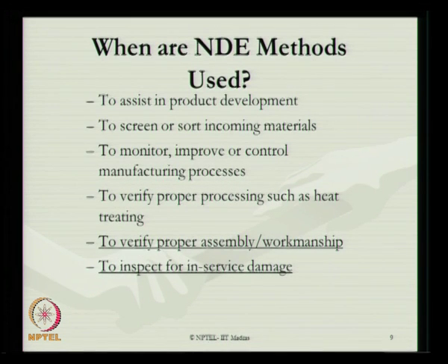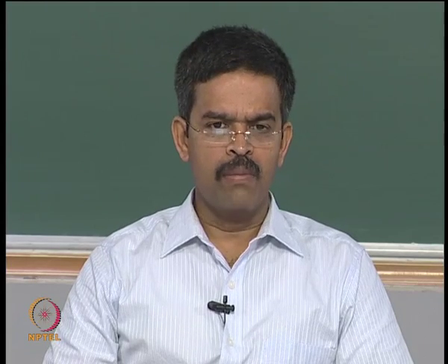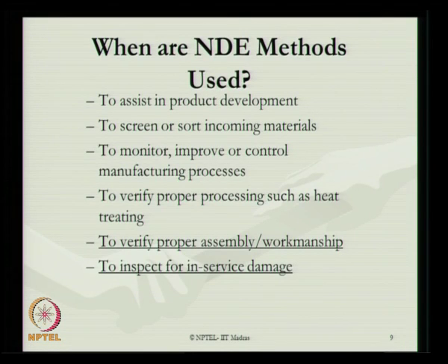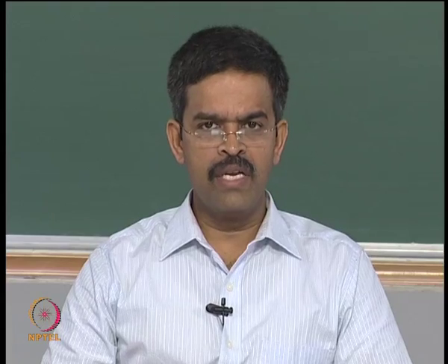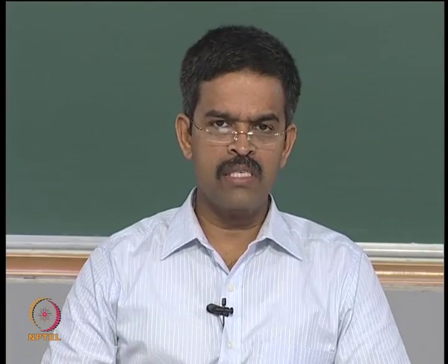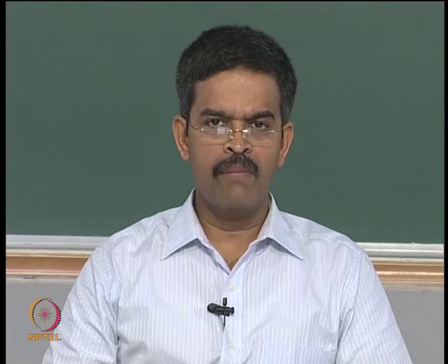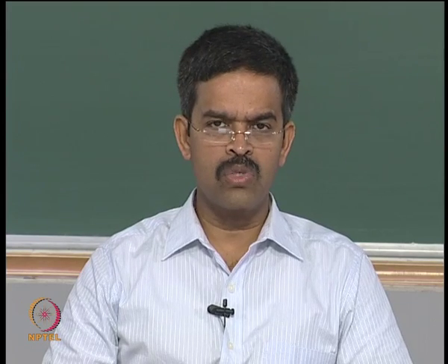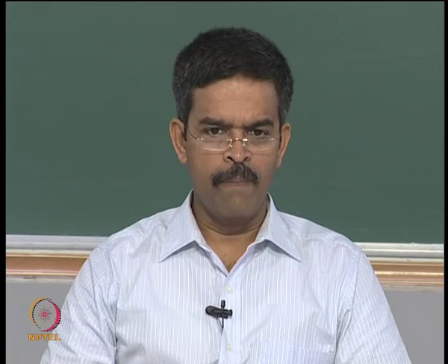Now the question comes, when are NDE methods applicable? To assist in product development, to screen or sort incoming material at the inventory stage, to monitor, improve or control the manufacturing process, to verify proper processing such as heat treating. As you understand, ladies and gentlemen, in offshore material selection, the heat treating process is considered an important stage, based on which the properties and mechanical characteristics of the material used for marine application are listed in international codes, for example API RP2A.